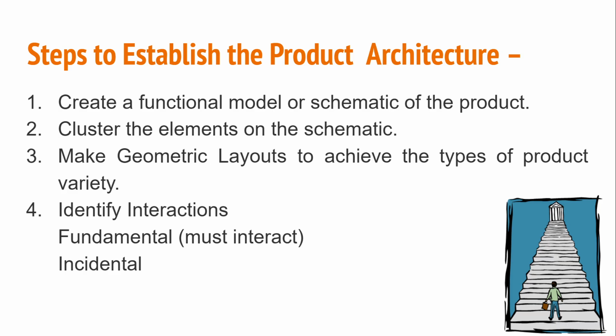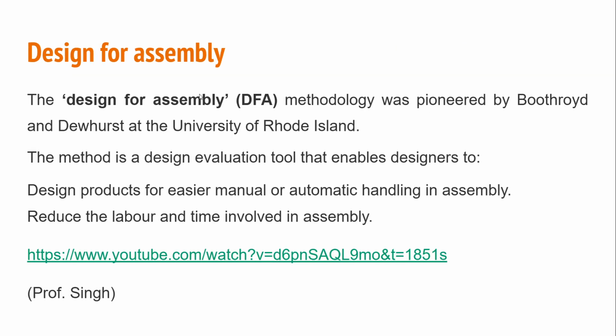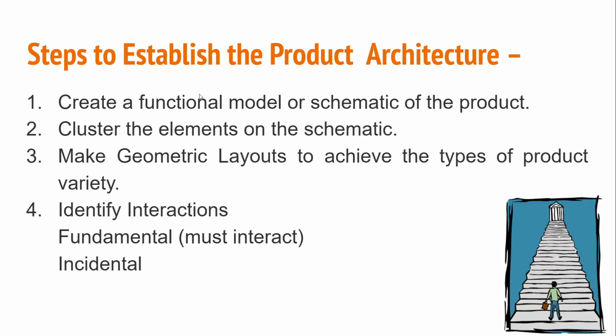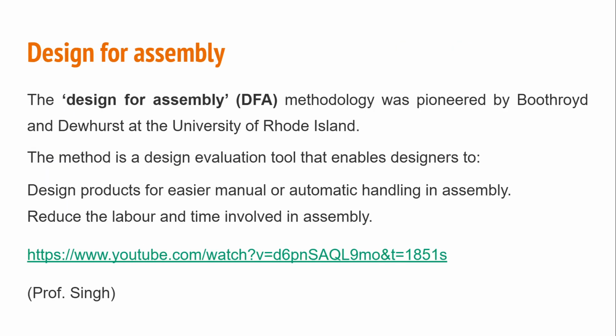Create a schematic of the functional elements, cluster the elements of the schematic, third, make a geometric layout to achieve the types of product variety, and identify fundamental and incidental interactions.